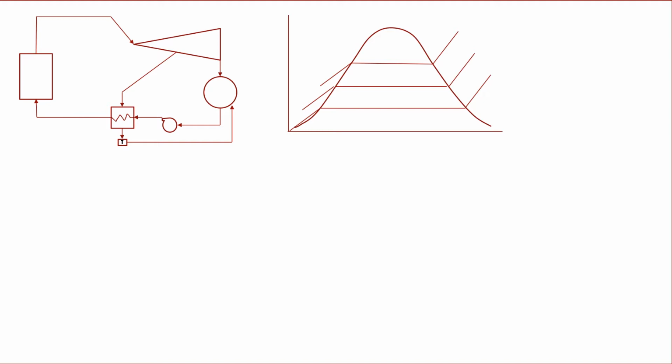First, we have here at point 1 with pressure 1 and T1. Now the steam expands to pressure 2, but a mass M2 has been extracted while the remaining mass continues to create work at point 3 with pressure 3. So the remaining mass here is 1 minus M2. This is 4. It goes out from the condenser. It rejects heat. It goes inside the pump. It increases the pressure at 5.